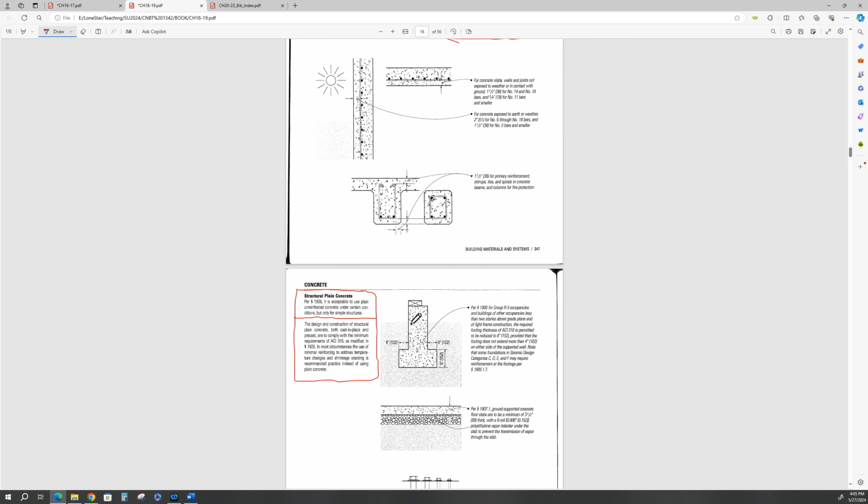If this was a small planter retaining wall, this has a sill plate on it, and you're going to put wall studs on it. You do that, I'm going to fire you. I will fire you in a heartbeat. Okay? At very minimum, you need temperature steel, just to keep it from having shrinkage cracks in it.